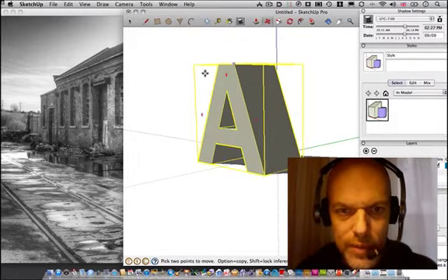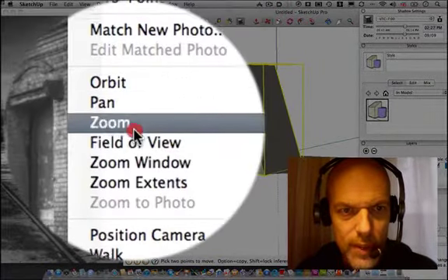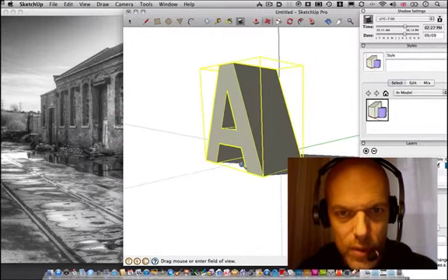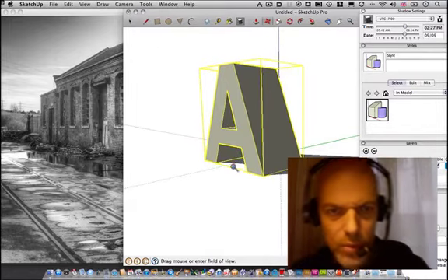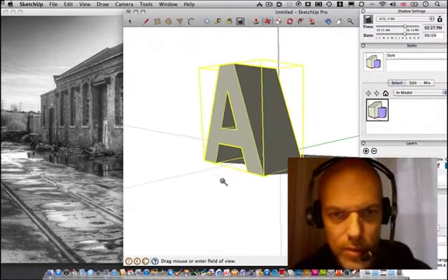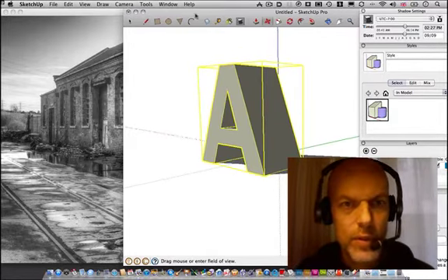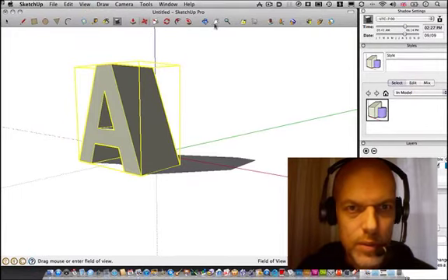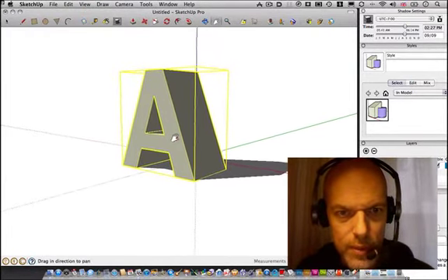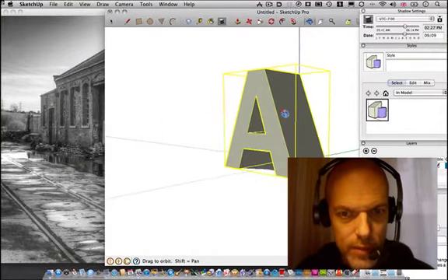Okay, you notice the perspective isn't exactly the same because of the angle there and the angle there. If it's going to appear roughly here, it needs to tweak a little bit. So what you can do is just go to field of view. What that does is it allows you to twist the perspective, because it's changing it from a wide angle lens to an isometric lens. Okay, so we want it to be around about there. Okay, that's one way of doing it. I'm going to just show you this in Illustrator. Okay, what we need to do is make sure we place it in the center, roughly with the right angle of the ground.